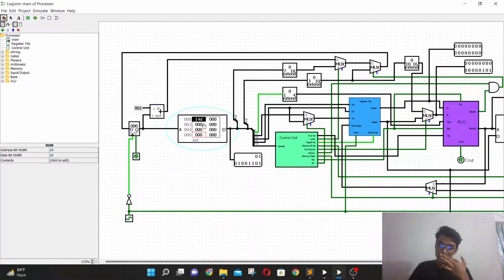So now the operation that is going to happen is that the value from S1 is being taken from the register file. This value along with the immediate 5 is being inputted inside the ALU, where in the input pin A, the value of S1 is being stored, and in the input pin B, the value of the immediate is being stored. After that, the result from the ALU is going to be written inside the register file, as you can see here in the write data.